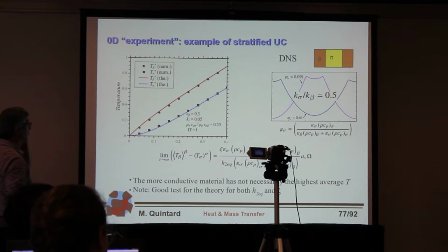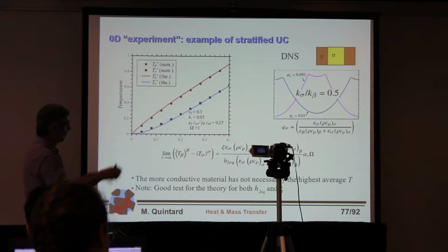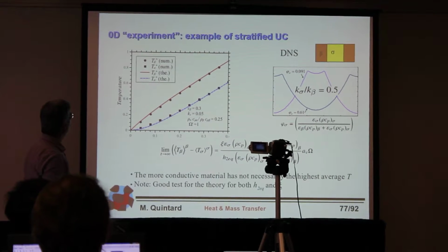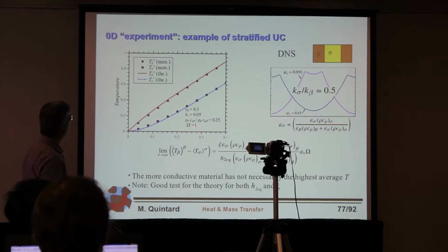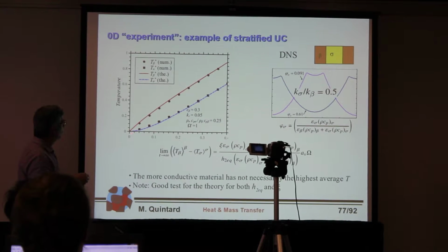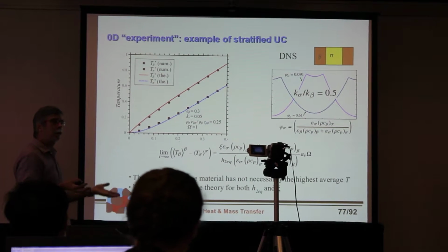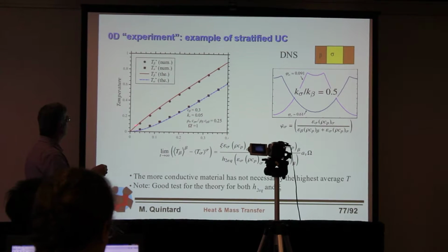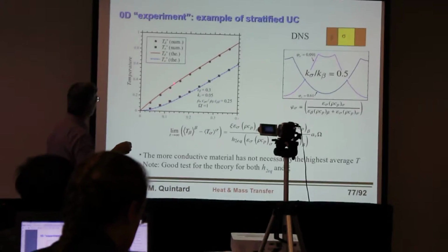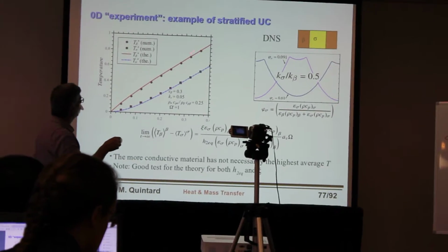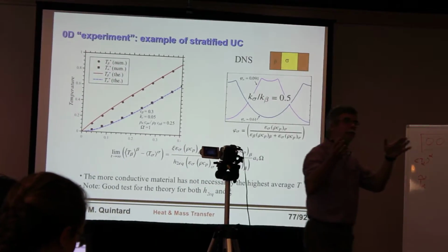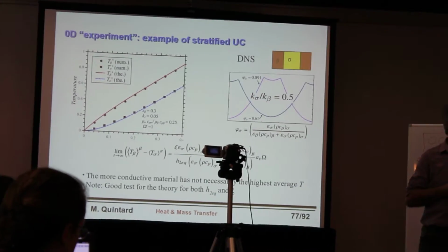I have a stagnant system, and then so homogeneous temperature, and then I introduce some heat at the interface, and basically I will have the following situation: the temperature of both phases at the macro scale will increase. There will be a transient evolution. Everything is transient, but if I look at the difference between the two macroscale temperatures, then after a while, the two temperatures increase, but the difference remains constant.